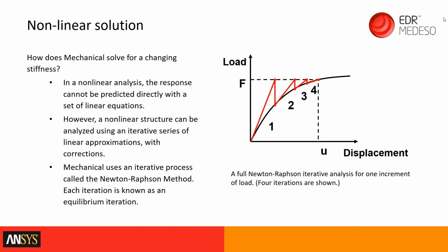Okay, what are the implications of doing a nonlinear analysis? When you're doing an FE analysis, what are the implications of introducing nonlinearities? Well, in order to solve the stiffness, we have to do it in a piecewise manner. We have to do it in iterations. Essentially, codes like Ansys will try to solve that solution in iterations.